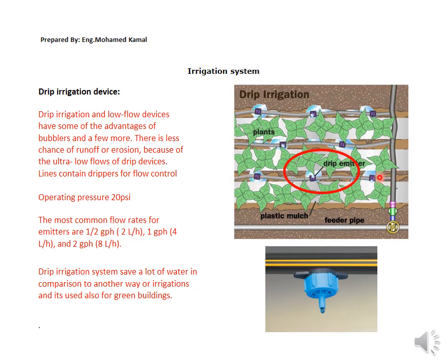Each line in the grid of the drip irrigation is parallel to the plantation line. So if we have a shrub plantation, we will have a line parallel to the shrubs. The distribution of the emitters is commonly 0.5 meters between each emitter and the other, while from one grid line to another, it follows the distribution of the shrubs itself.